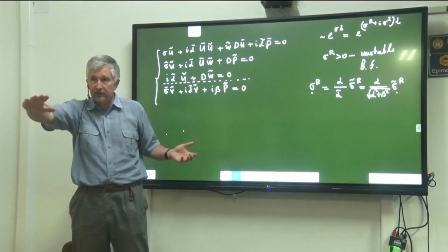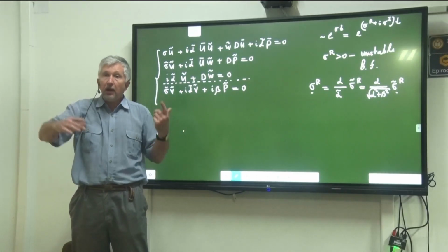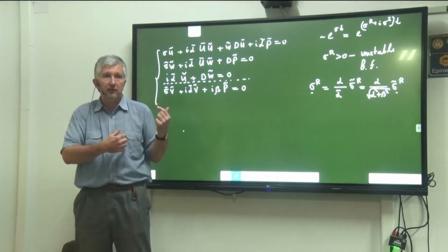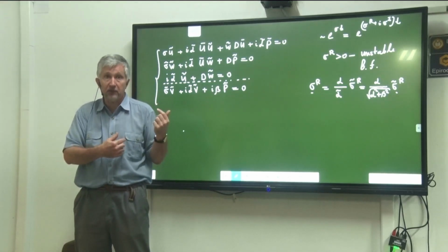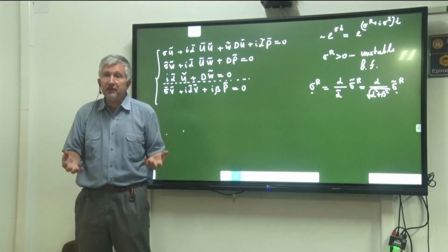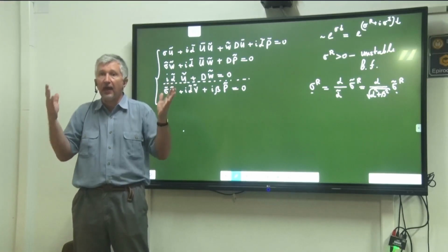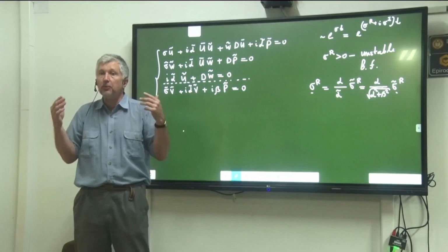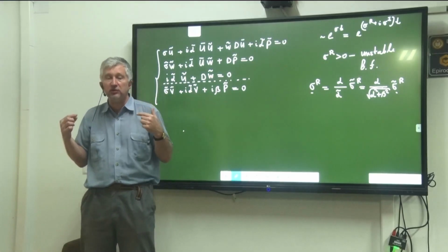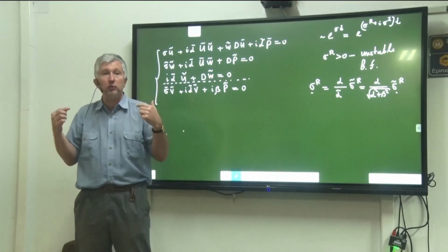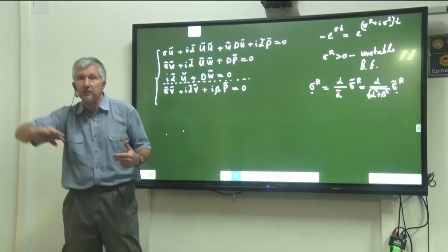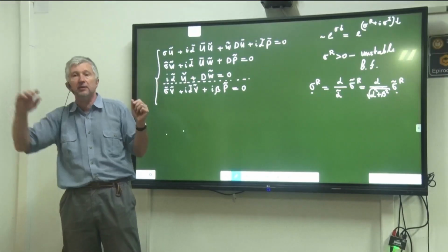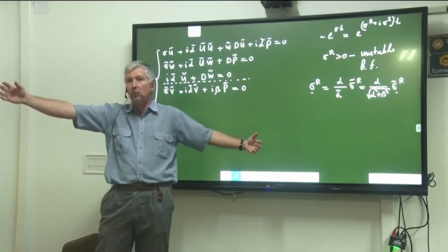It's just constant in y direction. And if v is equal to 0, there is no flow in the y direction. Agree? So if beta is equal to 0 and v is equal to 0, we have truly two-dimensional perturbations, which means the perturbations behave non-trivially in time, and they behave non-trivially in x direction. So they have a periodic wave in x direction. Alpha is not equal to 0, so they are periodic in x direction, but nothing happens in the y direction.